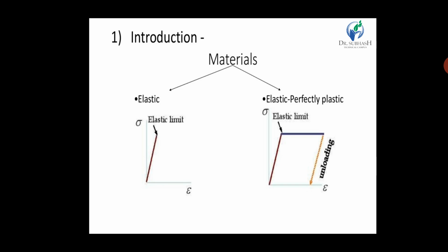The working stress method utilizes the strength of steel up to yield stress, while the plastic method utilizes the strength of steel beyond yield stress. You can see this in the graph of the elastic limit. The plastic method of design utilizes the reserve strength of steel beyond the yield strength up to the ultimate load point.